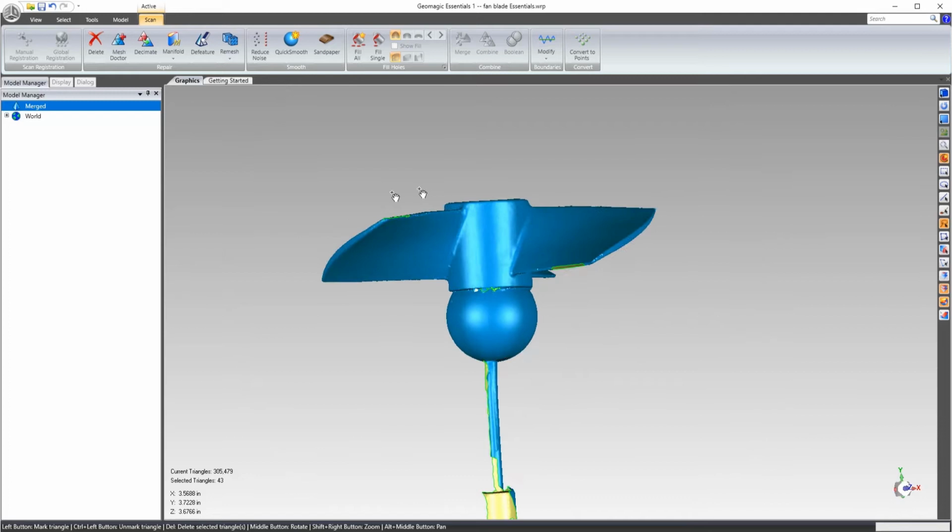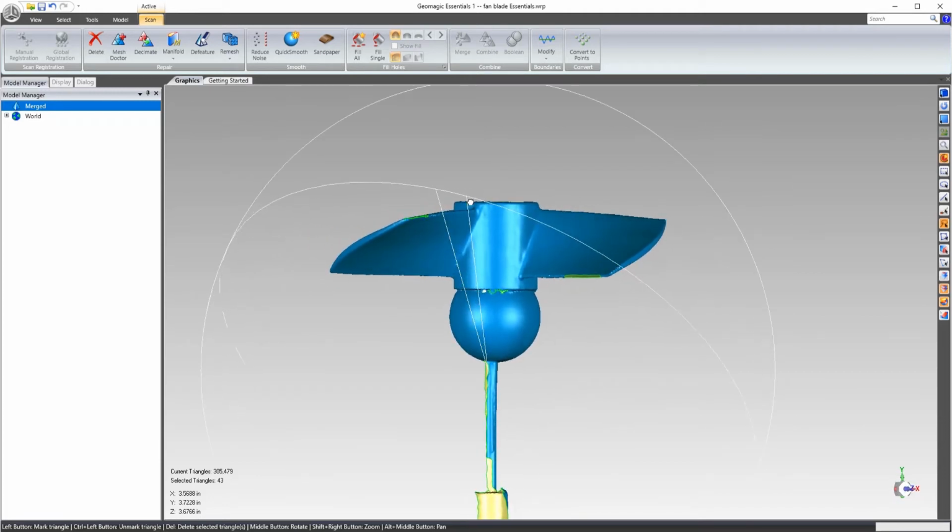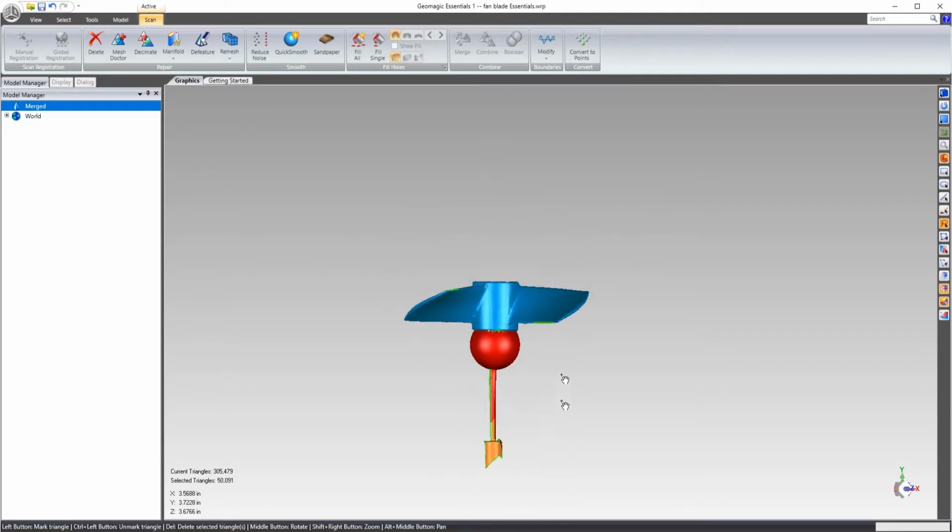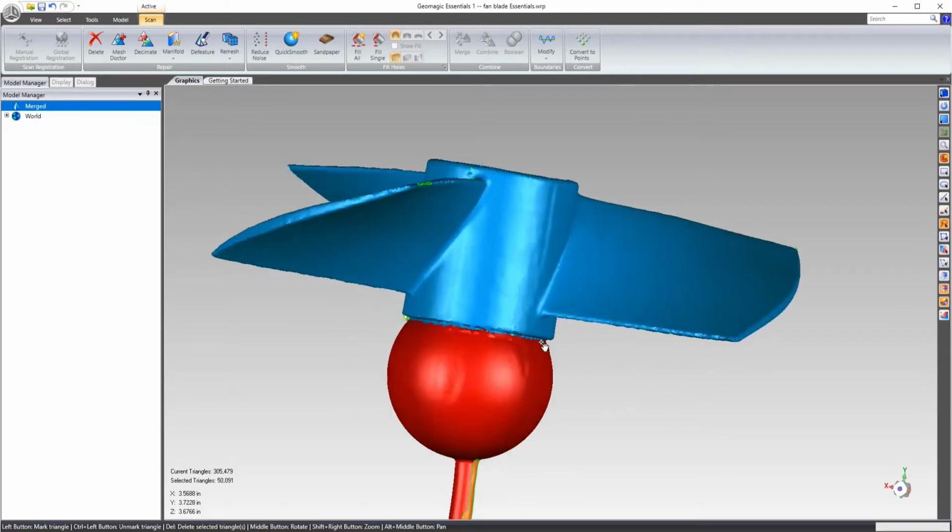So if I want to remove that bottom area, I can just look at it from the side, and I can grab tools from the right hand side over here. In this case, the lasso tool. And then I'm going to change it over to select through. Now with this, I can window in and select through, and you'll see that it'll go all the way to the other side.